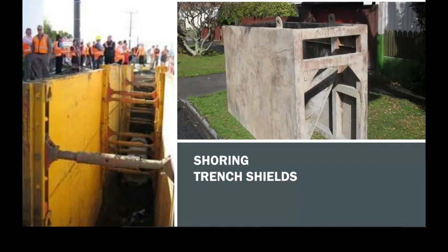Whereas this one, the trench shield, is just a protection for you. So it doesn't actually support the trench face. It may sit inside the trench face. It just means if the trench does collapse, you're still safe. So there's a slight difference between the two.